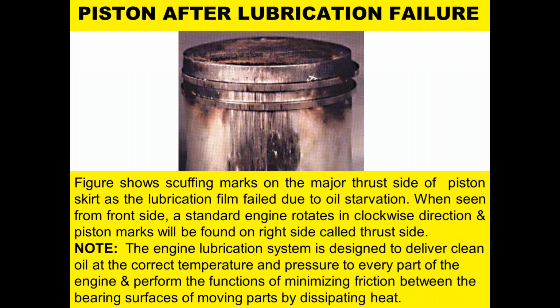Piston after lubrication failure. This is the piston, and this is the thrust face of the piston. The figure shows scuffing marks on the major thrust side of the piston skirt as the lubrication film failed due to oil starvation. When seen from the front side, a standard engine rotates in clockwise direction, and the piston marks will be found on the right side, called the thrust side.